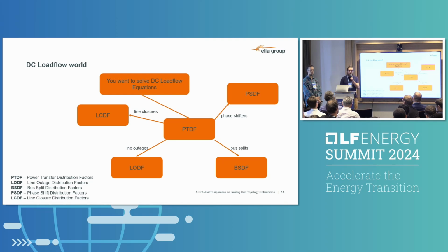So yes, we do a full n-1 analysis. We can outage branches via the LODF formulation. We can outage generators via the PTDF, just as the delta P. We can outage three-winding transformers with the MODF formulation. And we can also outage buses via the MODF formulation and PTDF formulation combined.